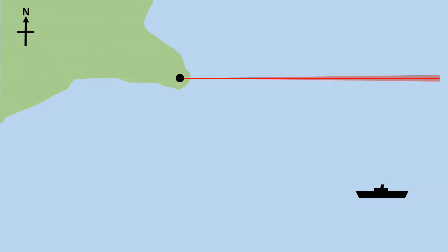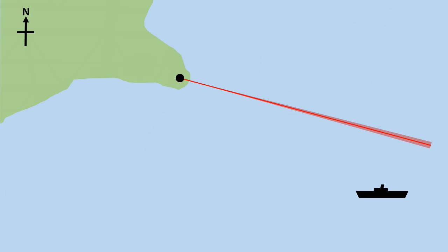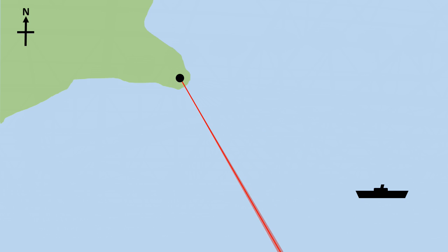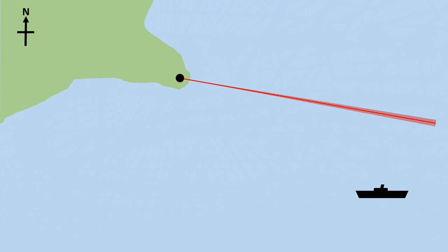Most descriptions of how a VOR works start with an analogy with a lighthouse with a revolving beam of light, so I'll do likewise. Here's a lighthouse on a headland overlooking the sea, and it sends out a sharply focused red light beam, taking 36 seconds to do the full sweep around the horizon, so that it moves at 10 degrees per second.